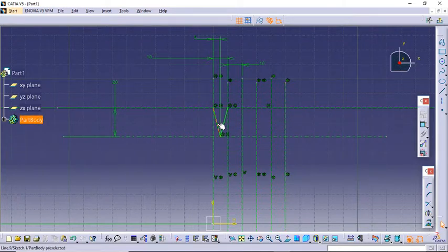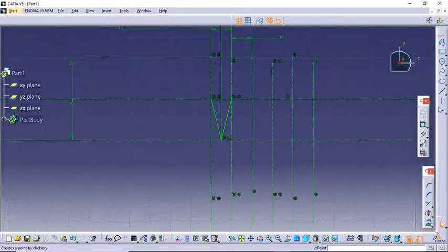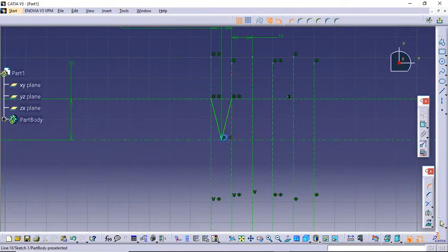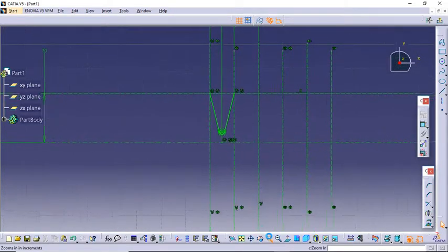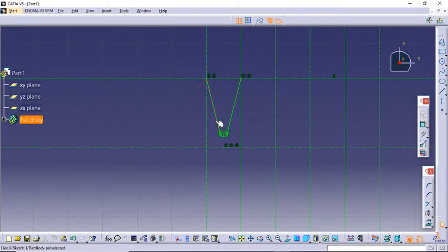Now I can smooth out this sharp pointy thing, which is actually required to remove the stress concentration. This radii I want only 1 mm, so it looks good now. Here you can see it has smoothened out.